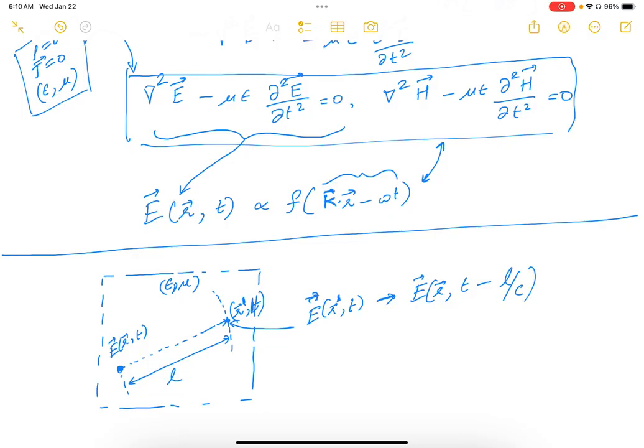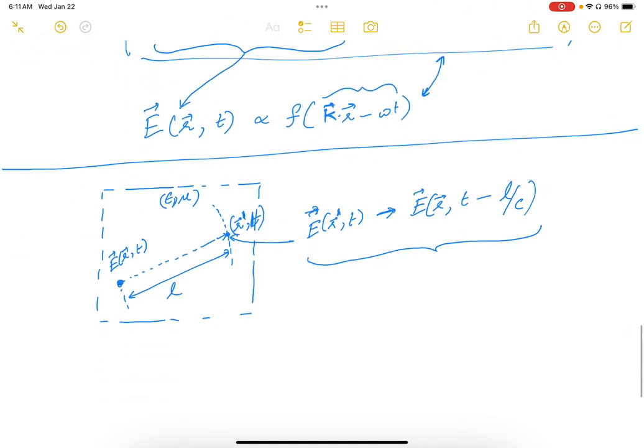So this, as we will see later on in the course, actually has a lot of implications for what kind of model we use to understand our link. So whether we go for modeling it as a waveguide, or as a transmission line, or directly as a lumped element, that really depends on the wavelength of the signal compared to the dimensions of the link that is actually carrying the signal.